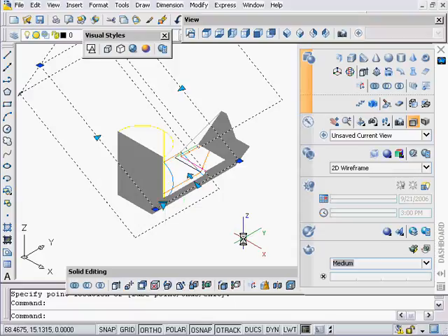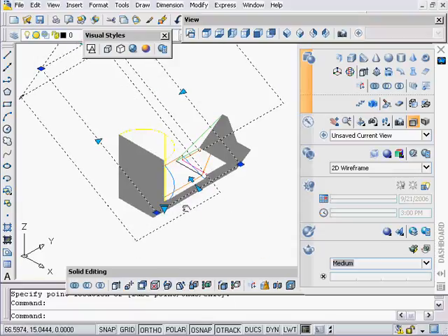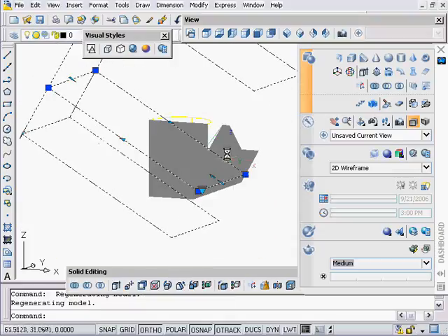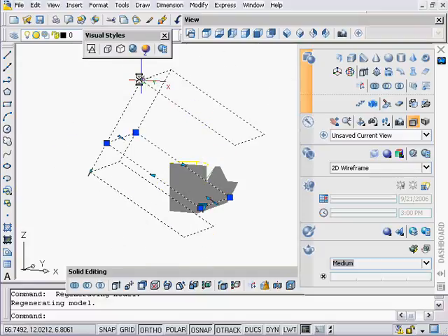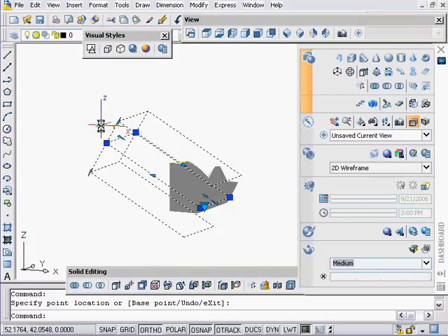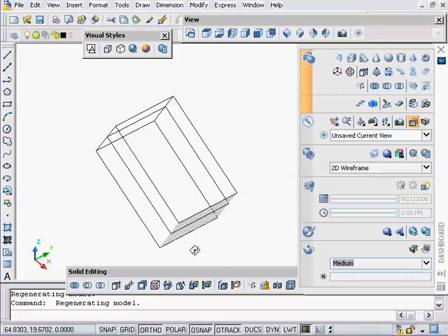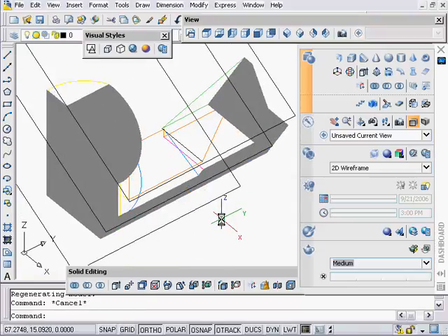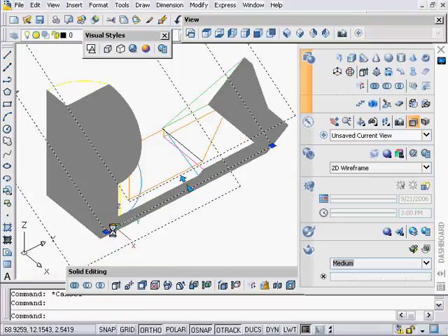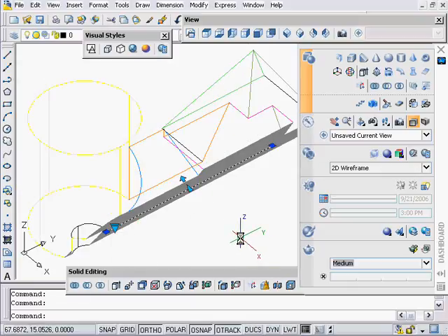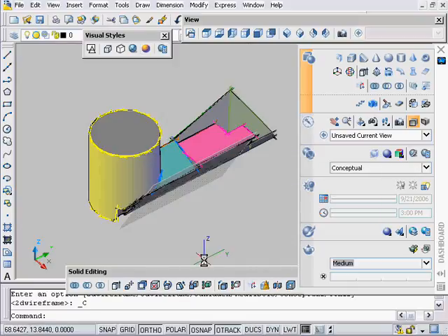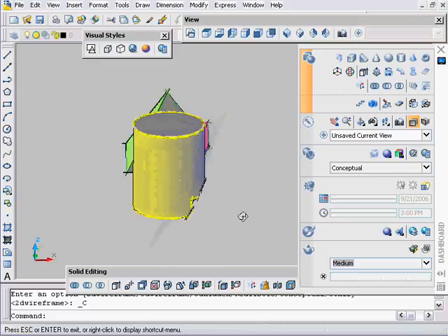Okay. Section boundary. Click on here. I want to see the section volume, which then has a 3D, shift middle mouse button, okay. 3D aspect where you can squeeze it down this way as well. Just insane how many settings we have on here. And back to section plane, okay.